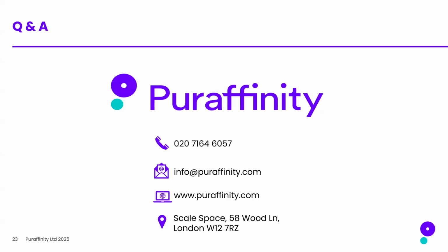Is G400 affected by background TOC levels, let's say around 12 milligrams per liter? We've done some work up to around 10 and not seeing any major impact. Obviously, the biggest challenge with TOC is what is that TOC? If it's large molecular weight TOC compared to small molecular weight, there may be some differences. So what we would recommend, especially at higher TOC concentrations, is probably to do some laboratory work. Either we could get a sample to you or potentially set up a pilot at the site. So we would again work with the end users on evaluating that.